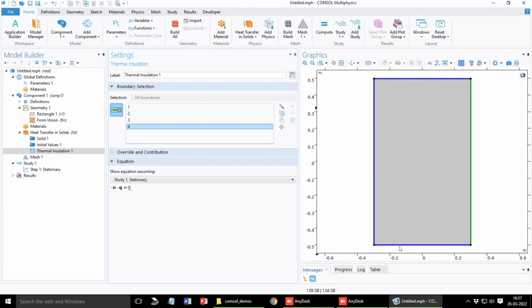Sorry, if you are considering these boundary conditions, the Neumann boundary conditions, which are generally applicable for adiabatic walls, this condition of minus n, which is the outward normal vector, dot q, which is the conductive heat flux, is equal to 0. So, for the right boundary wall, dT/dx is set to 0. For the top boundary wall, dT/dy is set to 0. Okay. Similarly, the left and the right boundary conditions are set in the appropriate way,